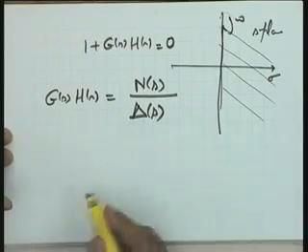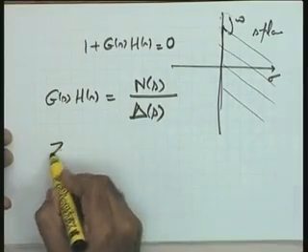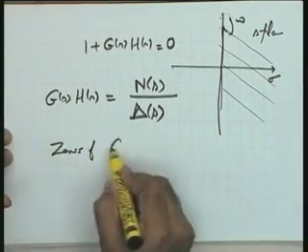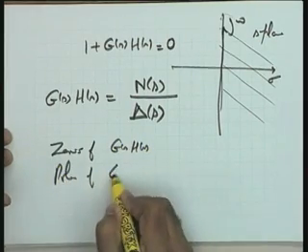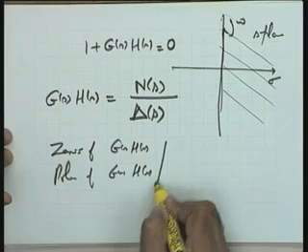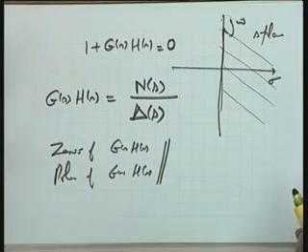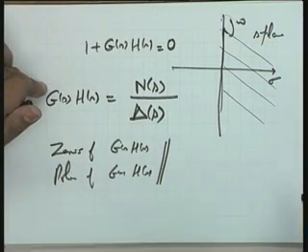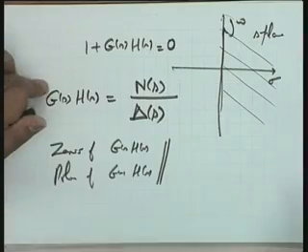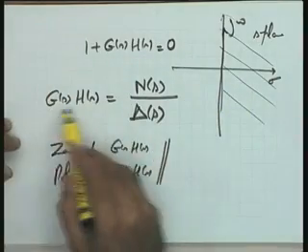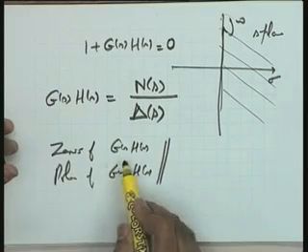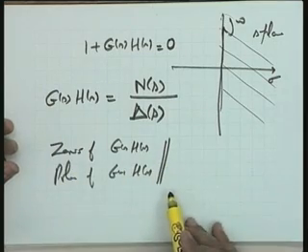So you will please note I say that the zeros of G(s)H(s) and the poles of G(s)H(s) are known to me. Please see that, because this is an open loop function, the process, the sensor, the compensator and all these transfer functions can be multiplied together to get me the value of G(s)H(s), and hence the zeros of G(s)H(s) and poles of G(s)H(s) are known to me.